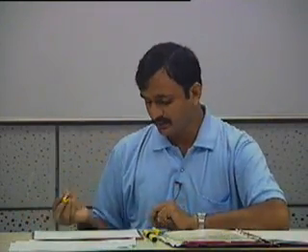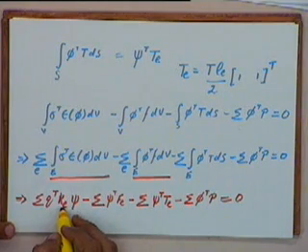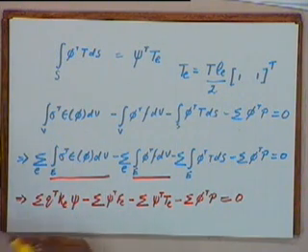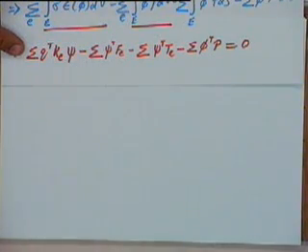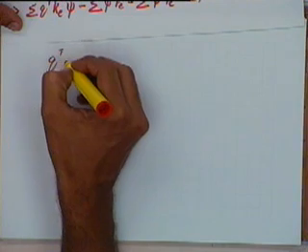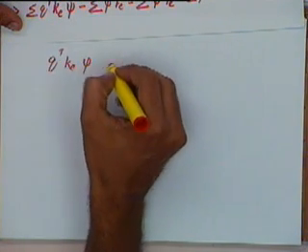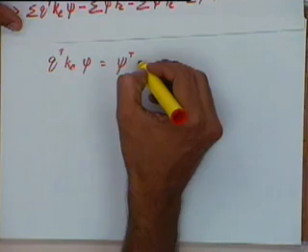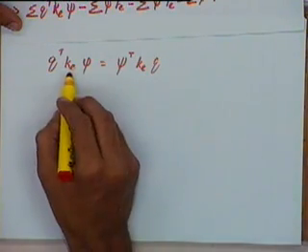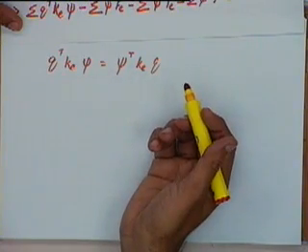Okay. And again Ke, the stiffness matrix, is a symmetric matrix. So just for convenience, Q transpose Ke times psi is the same as psi transpose Ke times Q, because Ke is symmetric and I can take a transpose without changing anything.